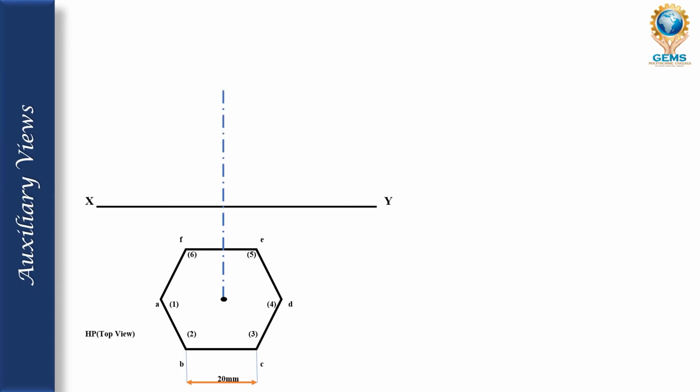Draw the center line first of all. In drawing, there are some rules. You have to draw the center line in this way: one line, one dot. One line, one dot. You have to draw the center line in this way only. Okay.